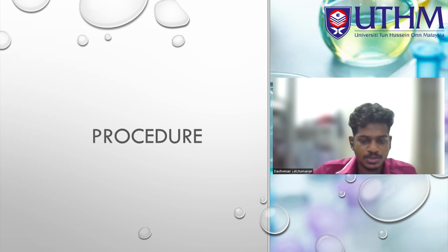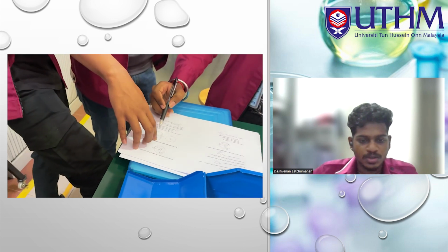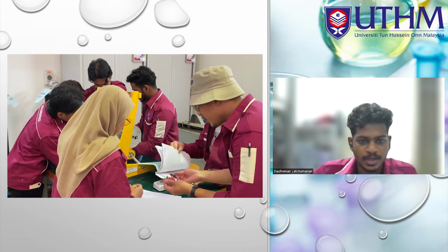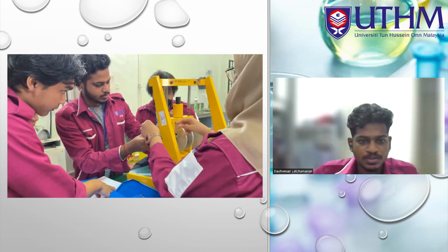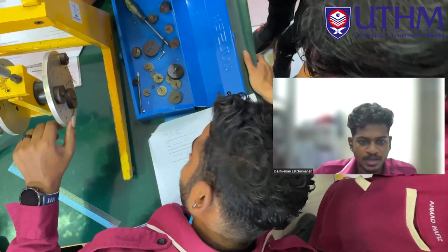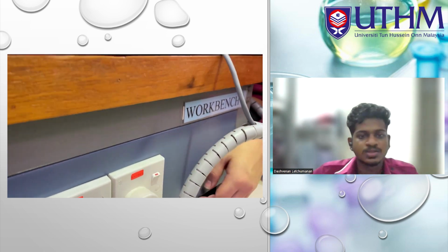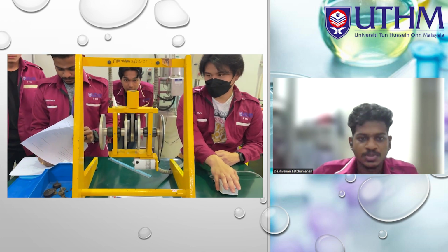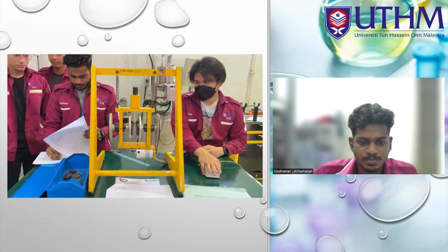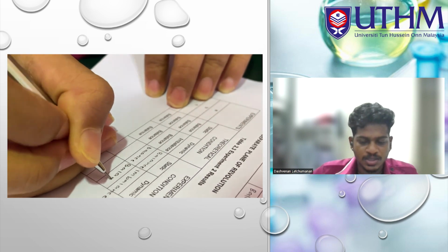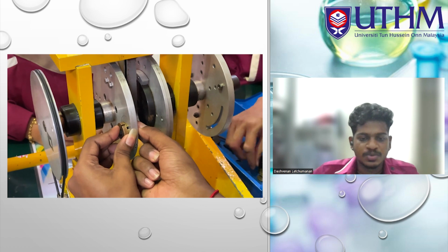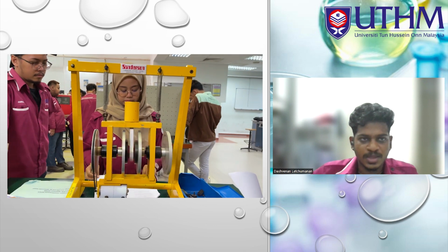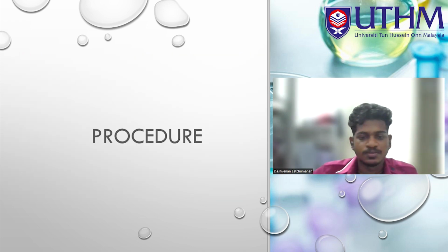The procedure is, first of all, we will review the lab sheet and find out the correct mass which needs to be connected to plate A accordingly. Then we will check and turn on the power of the accelerator and motor, and then we start to accelerate the system. The plate will accelerate and we need to find out whether the system is in balance or not by watching it perpendicularly and stating the observation in the result table. The procedure will be repeated for the multiple stages, plates A to D, and the mass will be placed accordingly to the lab sheet.